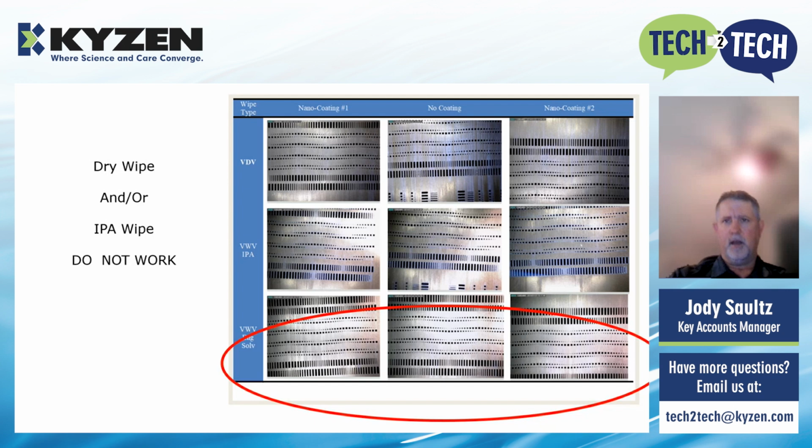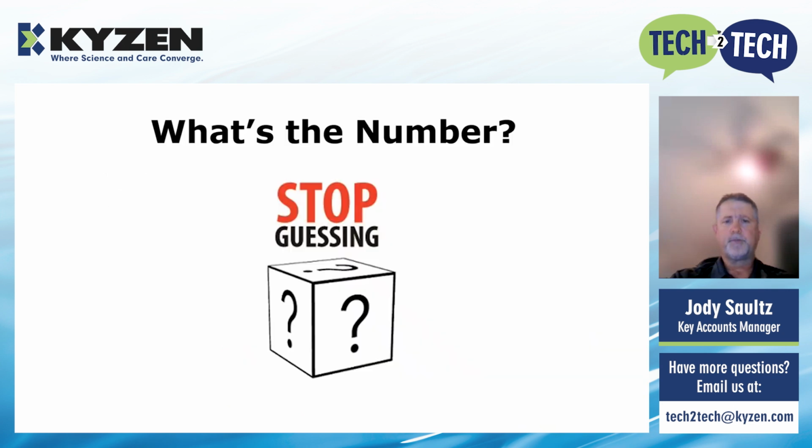But with the actual engineered solvent, you can see that the stencil is very clean. There's no paste in the apertures, and there's no paste that's been smeared throughout the top or bottom of the stencil as well. So we basically use the same parameters on these just to get a comparison, but the data doesn't lie. I mean, using an engineered chemistry can drastically improve your printing process.